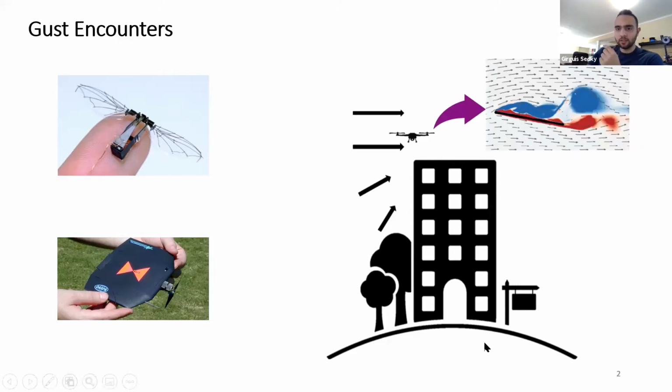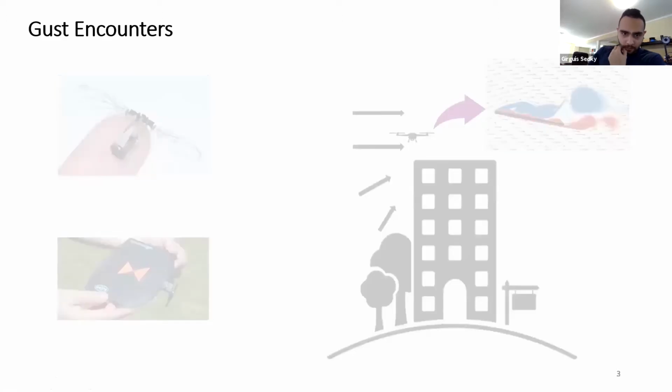Again, this is a CFD picture of what the flow structure could look like under unsteady conditions. You have flow separation, you have the formation of a leading edge vortex, you have lots of shedding and chaotic flow physics that affect the experienced lift and the forces on the wings. So to design these vehicles, we need to really get a better grasp of the flow physics.